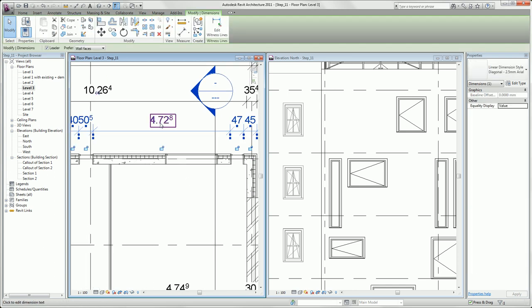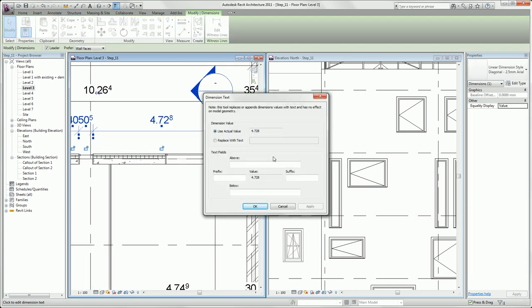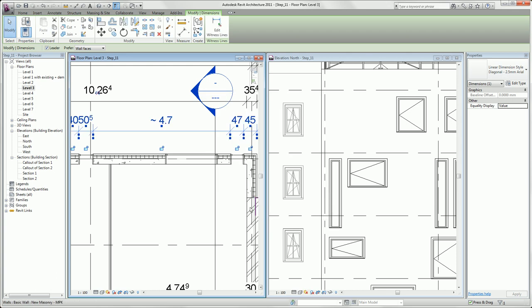Now we are going to place some dimensions. We double click on a value, and here we can click on replace text. And now we have to type in here a symbol. And we put in here 4.7 meters and we click on apply, and now this value has changed. The reason why we have to add a symbol when we override values is because that's an automatic security mechanism that you always know which values you have changed. Really important to know is that values which have been changed are not parametric at all anymore.